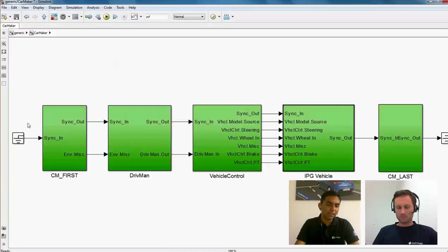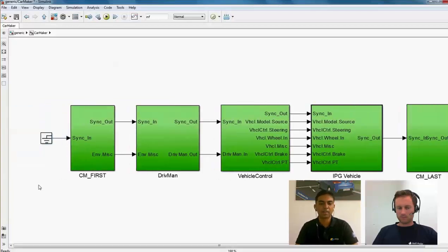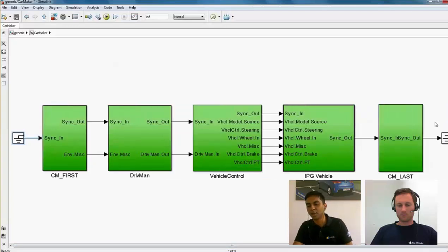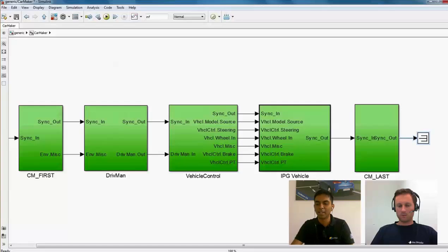Imagine if the environment is running on a hardware-in-the-loop system, then probably in the same flow we need to have I/O signals, which is like reading the voltage signals or current signals from the I/O cards, and this is done prior to the first simulation step. So you read in the signal, and writing back to the I/O cards is done at this level, after the end of the simulation cycle.